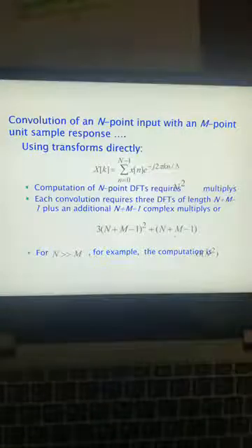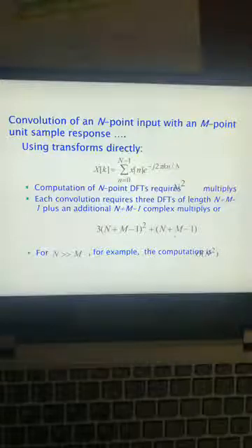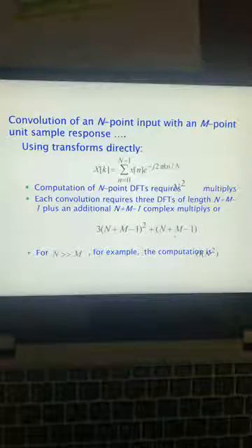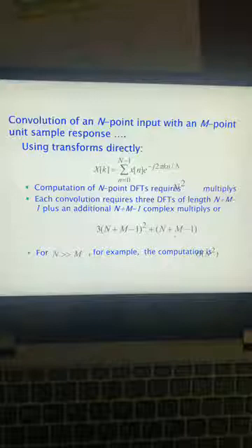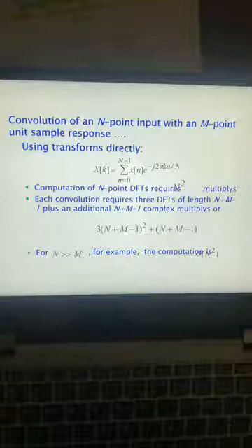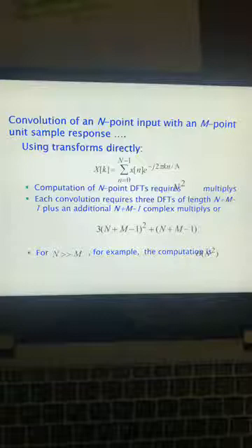Does the DC value add all the samples? Yes, the DC value adds all the samples together. So the DC value's amplitude is, as we know, just the sum of all the samples together. It may be 0, because if you have a sinusoid, its DC value will be 0. So not necessarily will it have a bigger amplitude. It depends on how much DC offset you have in the signal, and the DC value would tell you that. So we have covered this as well.